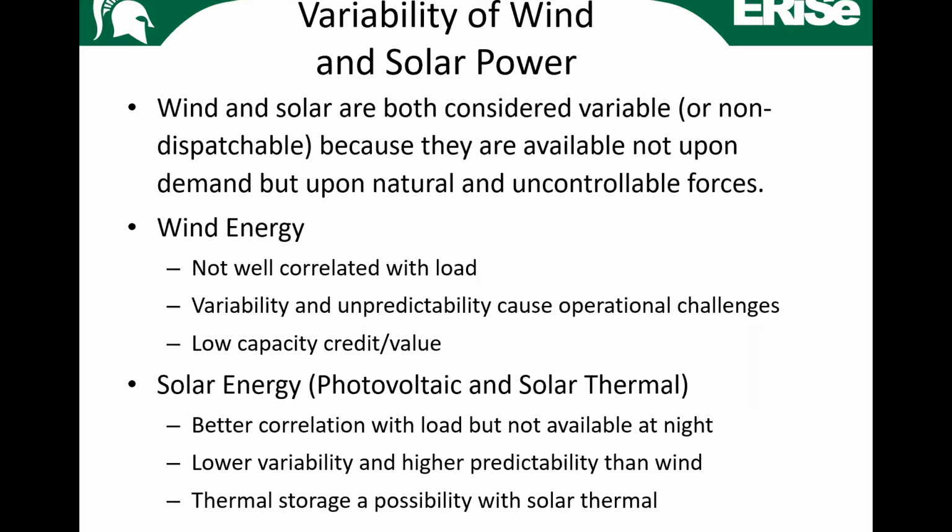Now, wind and solar behave differently, though. You'll see that wind is not very well correlated with load. Load goes up during the daytime and drops during the nighttime. And how many times have you noticed that on a hot summer afternoon, when you need the wind the most, not just to turn your wind turbines, but also to cool things down so the load on your air conditioners is less, that's when the wind decides not to blow, right? And in the evening, when you don't need it as much, that's when you encounter the most wind speed. So it's not very well correlated with load.